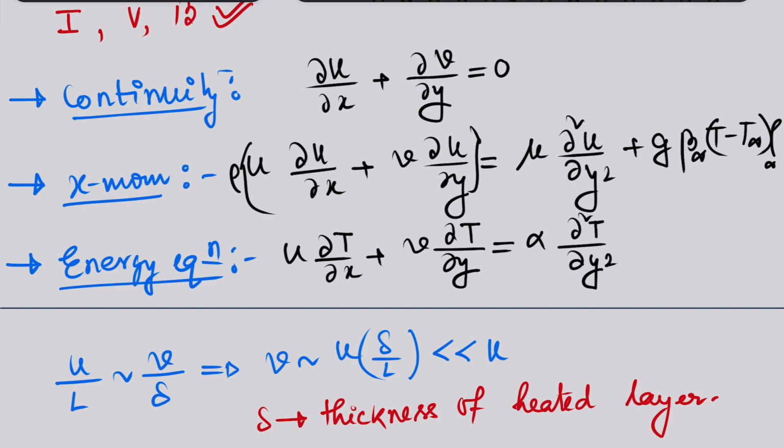Here we are considering that the flow is a very low Mach number flow, that is why we can say that the viscous dissipation is not important. Whenever you have other terms, you will see by the order of magnitude analysis that not all the terms are of the same order of magnitude.